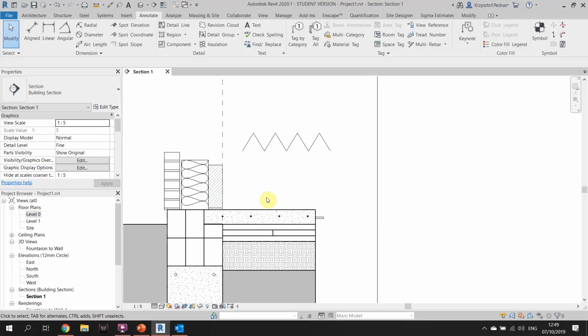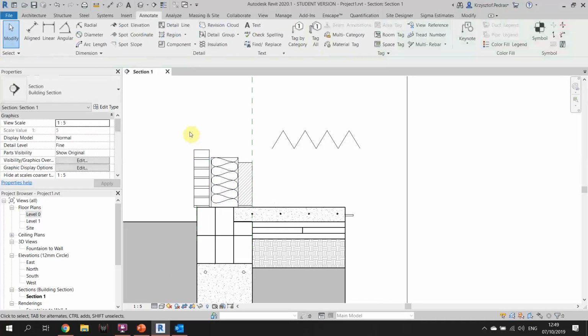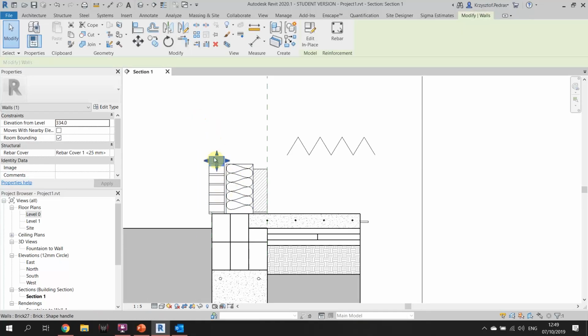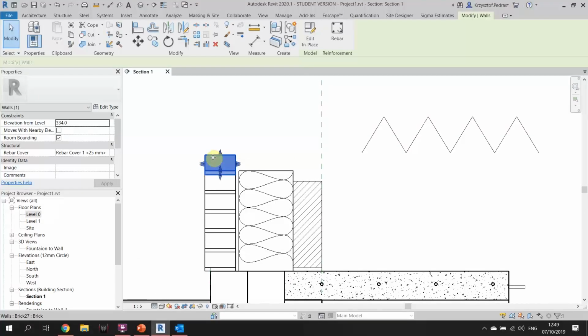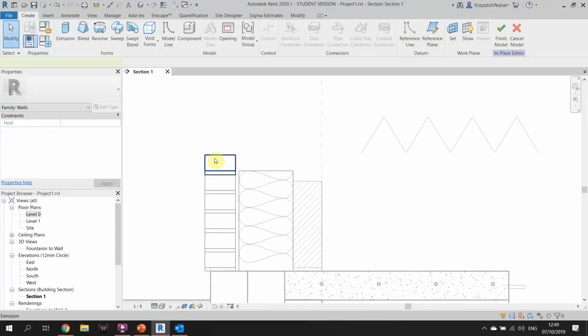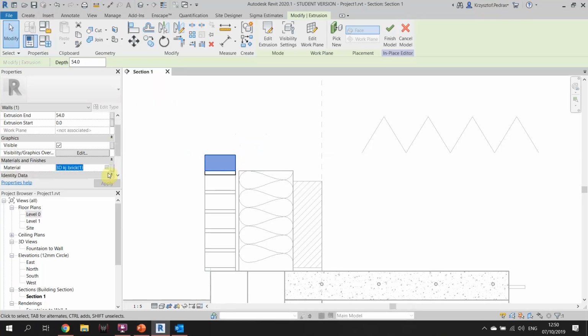Another way, if you create sections from a 3D model, what you can do, you can specify, because you're cutting from an existing object that has a material applied to it. So one way to get the hatchings done is to actually edit the material. I'm just gonna go inside of one of the groups. I'm gonna click on the brick, and I'm gonna edit the existing material that we created earlier.